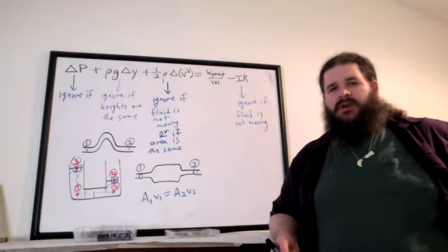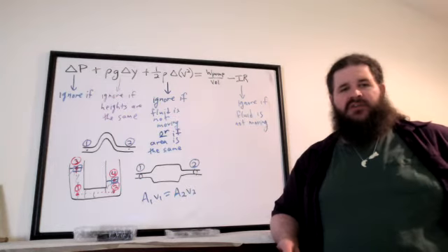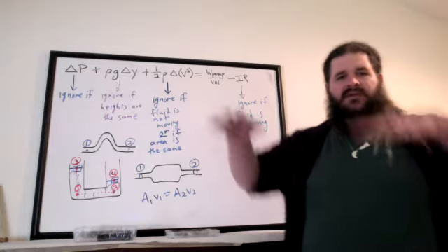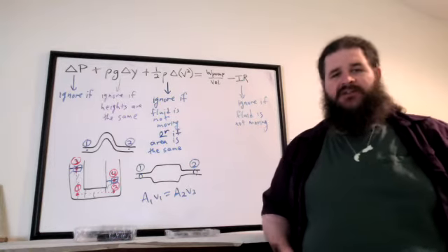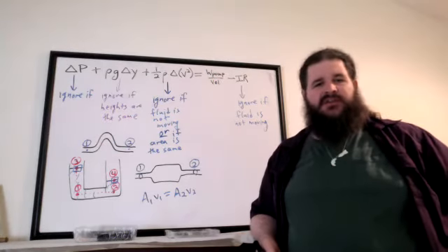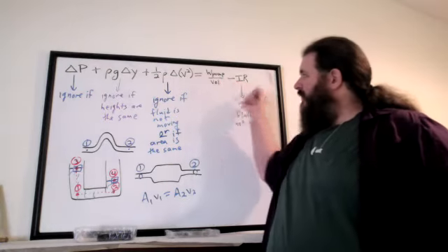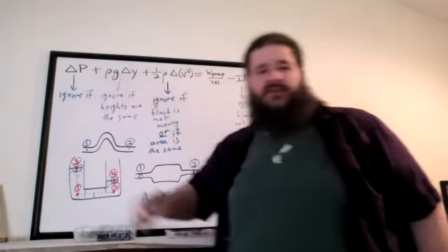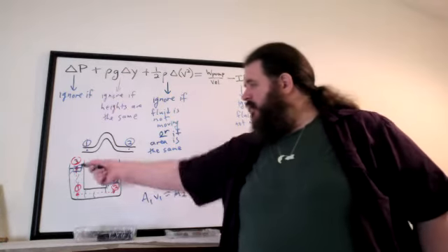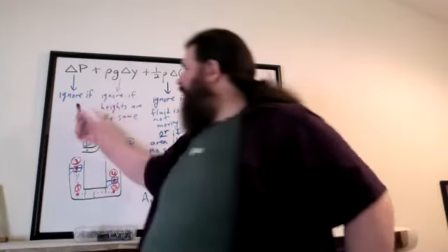So if there's some reason where you know that they have to be at the same pressure, you can ignore that delta P. And that's usually if they're both exposed to the same atmosphere, or if they're both exposed to the same pressurized gas tank or something. Or maybe you've got pistons pushing on both points with the same amount of pressure. So this one's kind of flexible. Usually you do want to include delta pressure to possibly balance out other things. Like if there's some other changes that don't cancel each other out, delta pressure is usually what changes to balance out everything else. But if there are situations where you know 2 points have to be at the same pressure, such as if they're both exposed to the atmosphere, then you can ignore this.